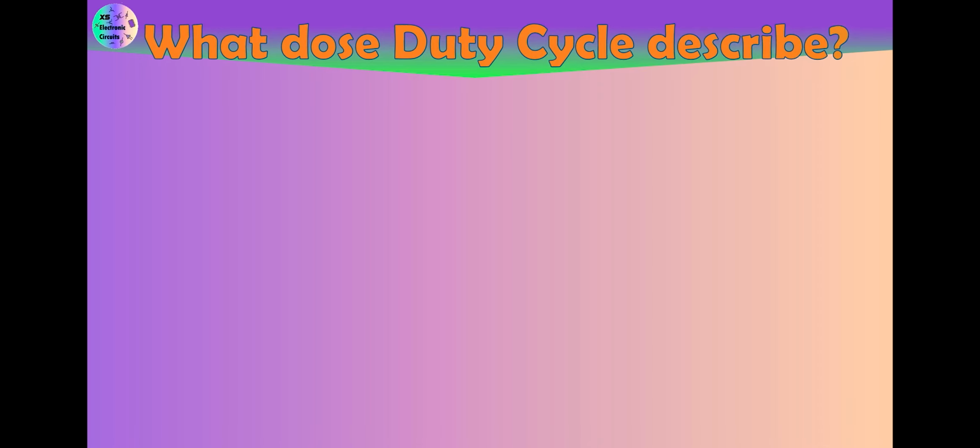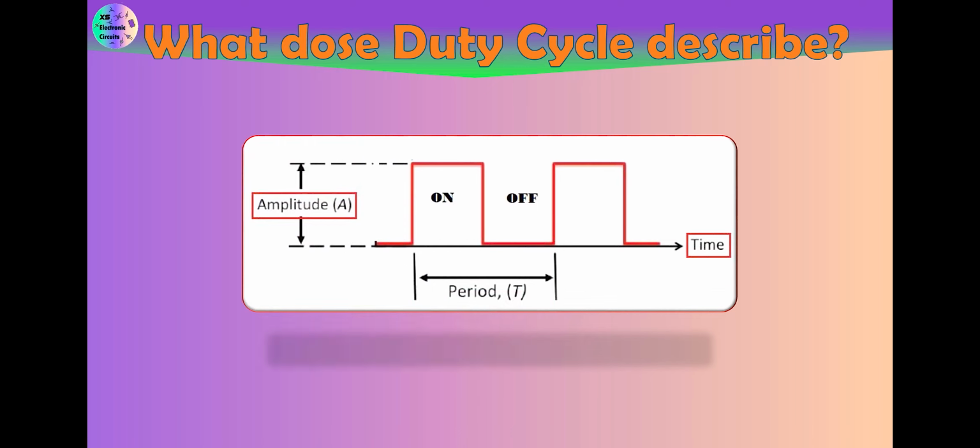To accurately describe the PWM signal, the concept of duty cycle must first be explained. In signals, we define logic high as on time. To represent the duration of on time, we use the concept of duty cycle. In simple terms, the duty cycle describes the percentage of time a digital signal is on over an interval or period. It is represented in percentage.